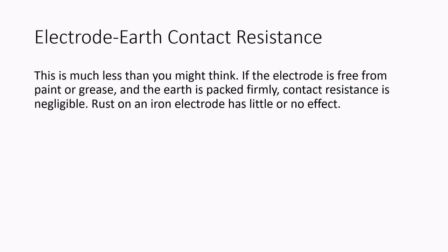Then we come to the contact resistance. So we talked about this earlier also. This is actually a very low value when you compare to the total earth electrode resistance. If your earth is packed with the earth electrode, the contact resistance will be a very low value. It is also negligible.